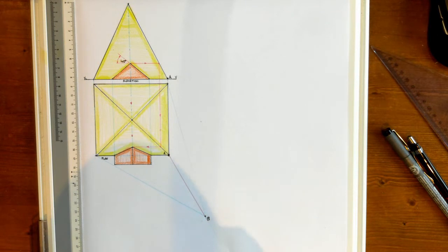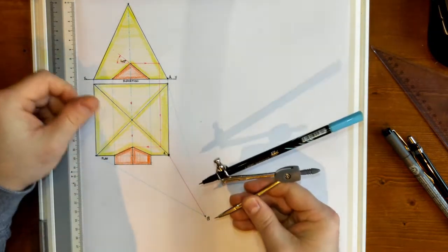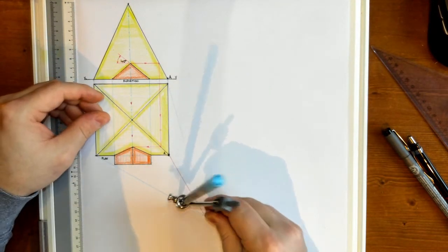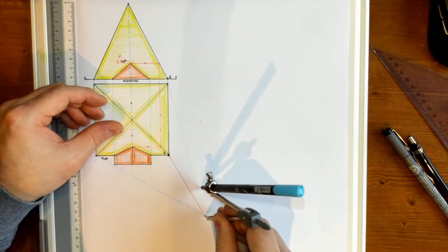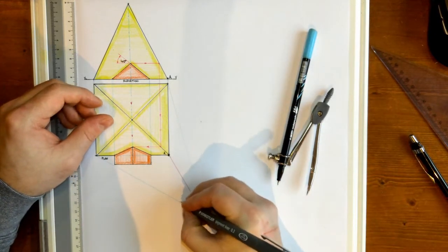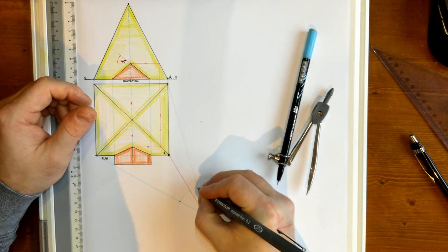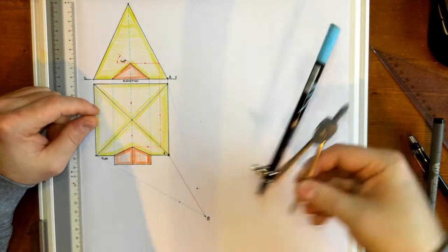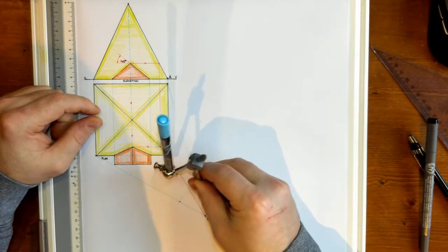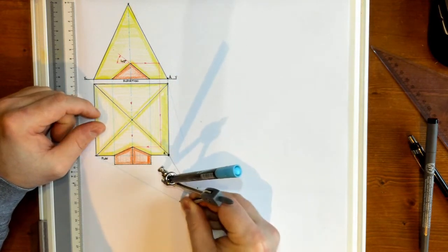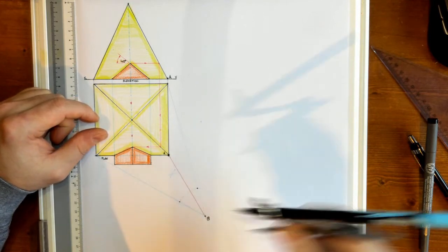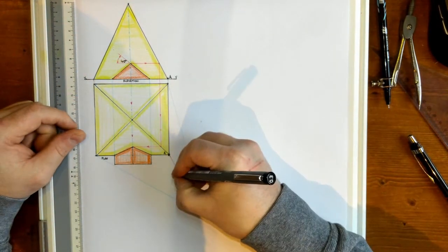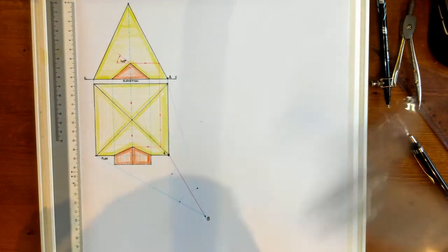So I'll take my compass. Now I'll use the small compass for this so I can put the colour in and show you a little clearer, because I want to make sure that we're all okay with what we're doing here. Any distance on the compass there, and we're going to swing an arc. Now that arc intersects the line here and the line here, 2 intersection points. Take the compass. Key thing here is that you keep the same distance on the compass for both arcs to bisect the angle. Now that point there, we will be able to draw our bisector through that point.